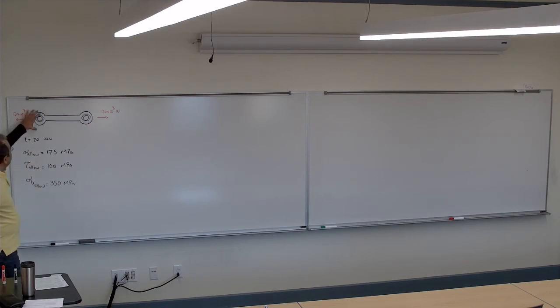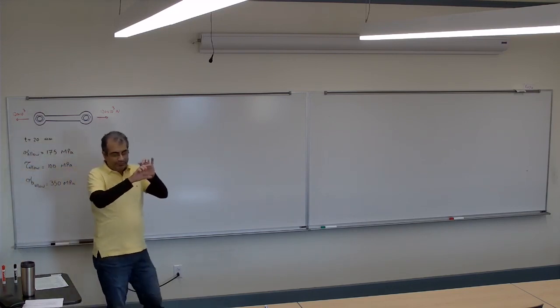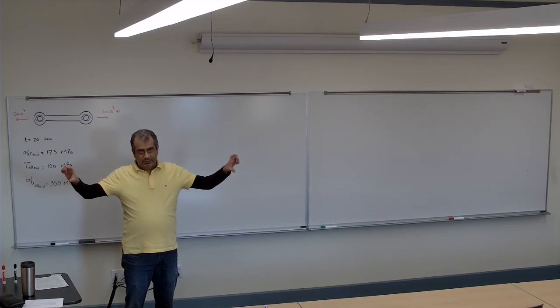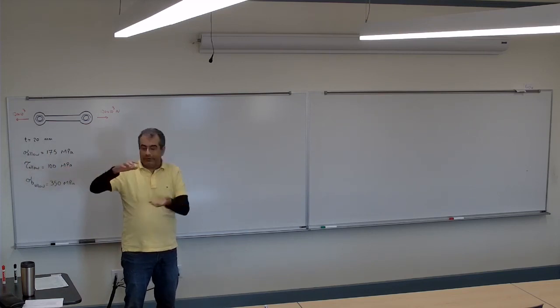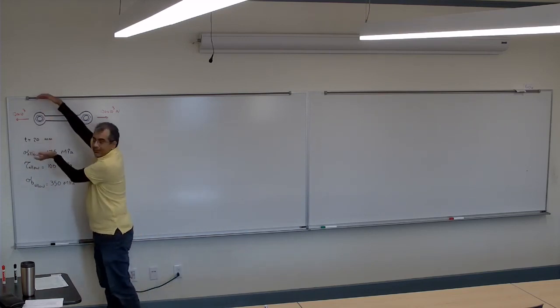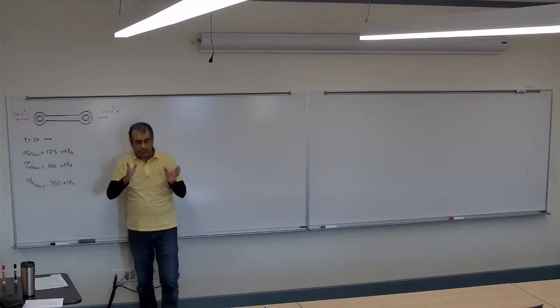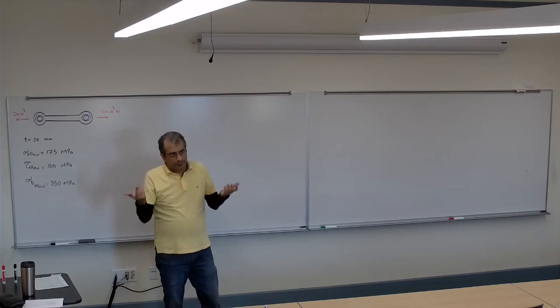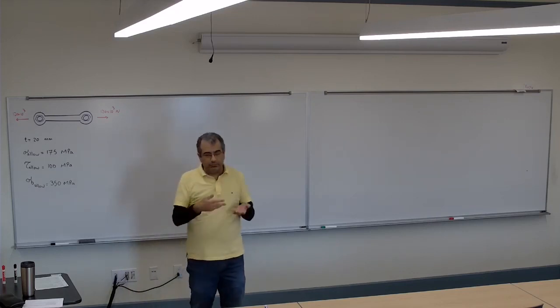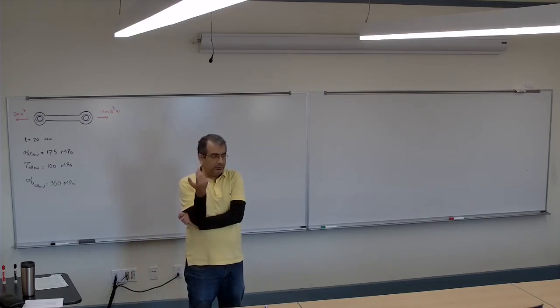But if I make this large enough, then maybe this becomes the weak point. So the hole is the weak point if the entire section has a constant height. But if, for example, here I make it very big and the hole very small, then it might be here. But I agree, just by looking at that, the weakest point is going to be the hole. So probably the first place we have to check is where we have the hole. Then what?